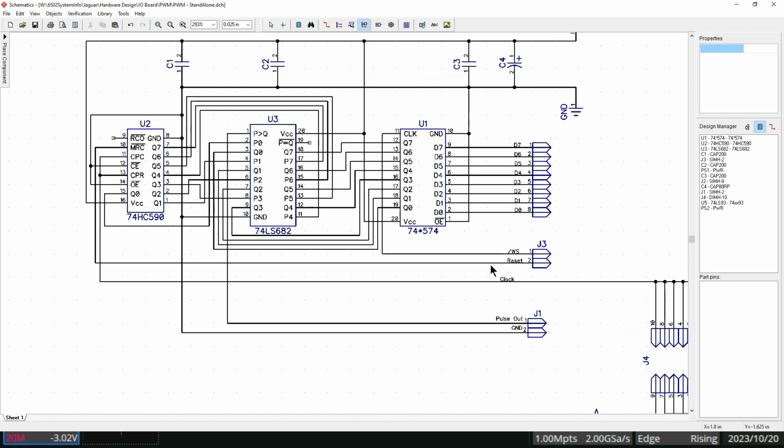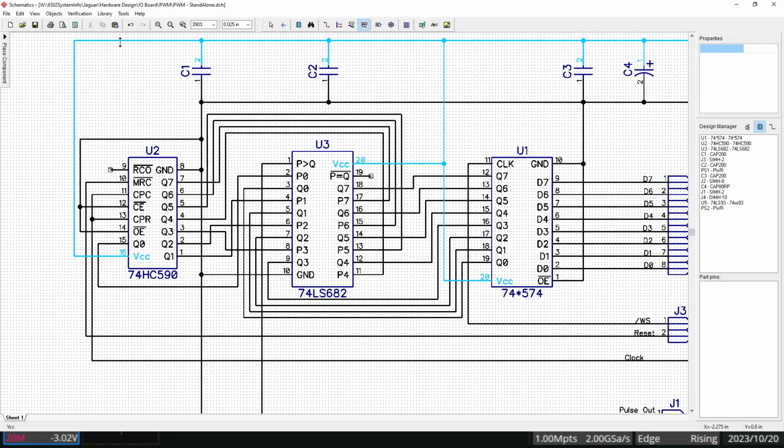And what it does, comes in here, let's look at these chips now. These are the most important ones. We've got a 74AC574, and it's a latch. So it latches the data bus when the write signal is given. So when I write to that location, which was 33,024, it gets a write pulse and it latches what's on the data bus. So when we poke a value to it, it gets that value.